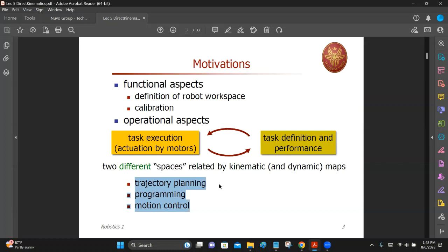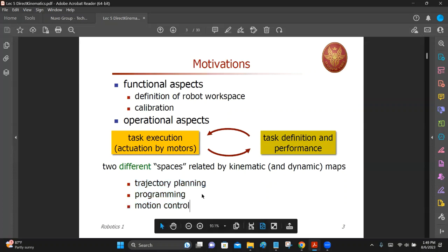So you have to convert your operation in our workspace into joint angles using, if it is a 5 degree of freedom manipulator, 5 joints. So every step of the way, every 50 milliseconds or so, you have to update the joint angles, all of them. Okay. So then you have to program it into the programming platform of the manipulator, right?